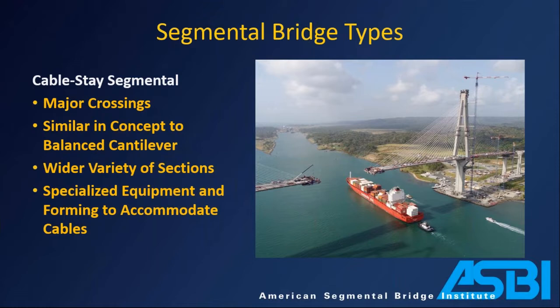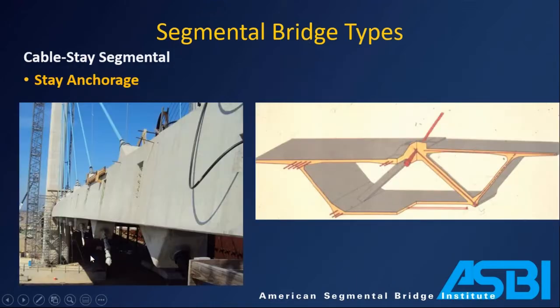The one major difference between the two, other than the cables obviously, is you need to find a home for these cables. You need to find a way to anchor them. You have a real big concentrated force in a real small area, so you need to find a way to put that force into your structure safely. And a couple of ways that you do that.